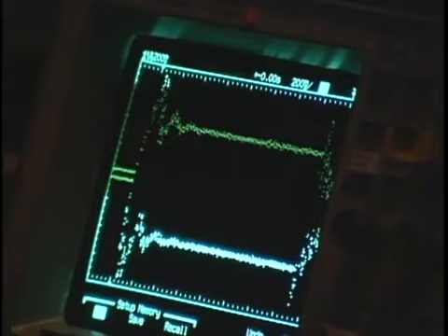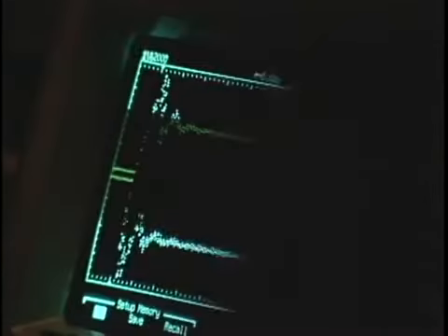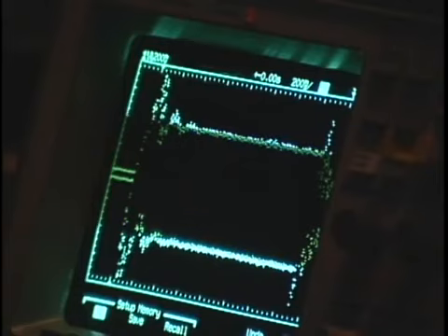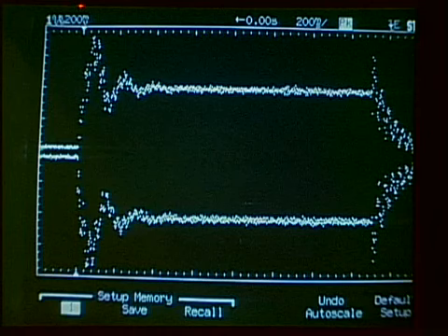In other words, if he has 581, and we measure here 575, which is this resonance, then the difference is 6 hertz, and we measured that from here to here is indeed 1/6 of a second. So 1/6 of a second, that means 6 hertz. So the oscillation that you see right at the beginning, when we start the driver, that oscillation is 6 hertz.